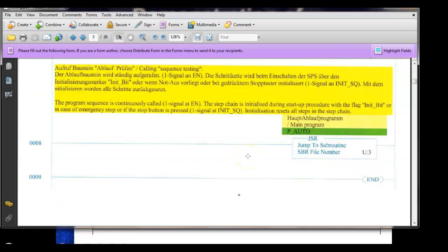So your main program is real short, because all it's mainly doing is calling subroutines. And now we can split it up. So we've got an emergency stop subroutine. If I was having problems with my e-stop, I wouldn't have to go through a big program. I could go right there. It's got a stop, it's got a reset routine. When you hit reset, it goes back and does a certain thing. Some of them are conditional, some unconditional.